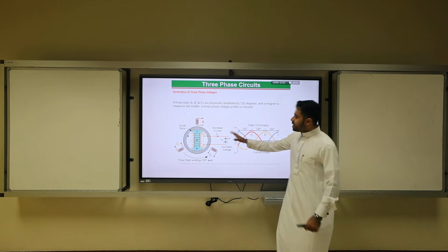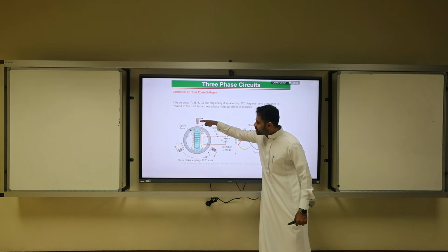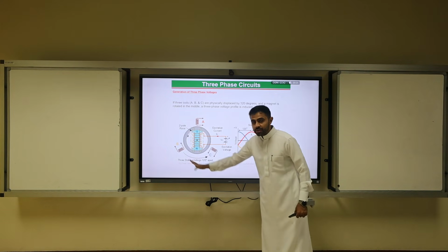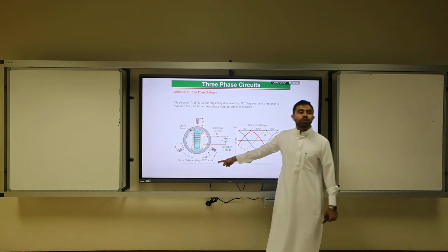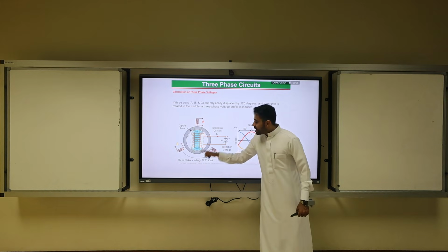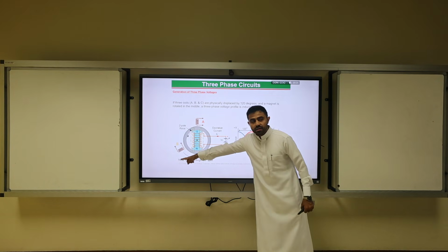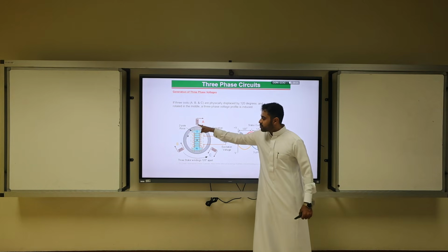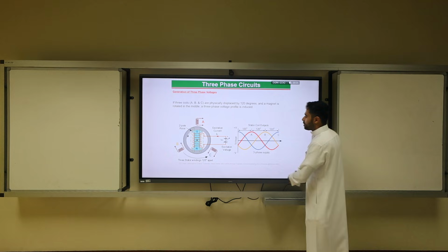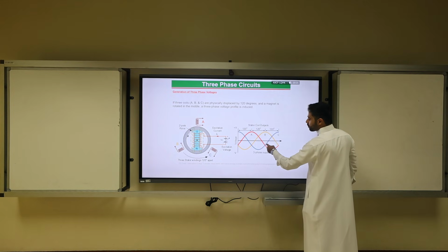Why do they come in 3-phase? In the synchronous generator, we space the windings of A, B, and C, the coils, by a geometric 120 degrees. Because of this 120 degree spacing, once the rotor goes here, the peak is here, not there. If it's peaking at C, it's maybe 0 in A and maybe halfway in B. For example, the peak of A is halfway of negative B and C. The peak in B is negative halfway of the other 2 phases, etc.